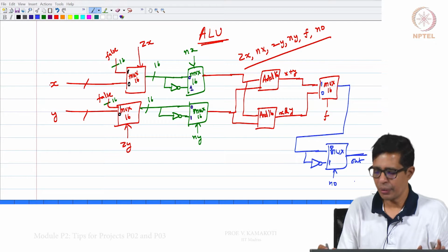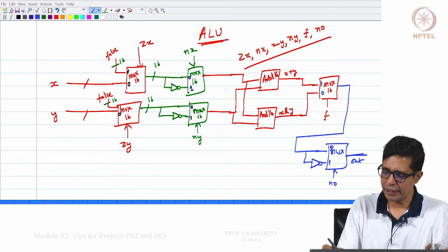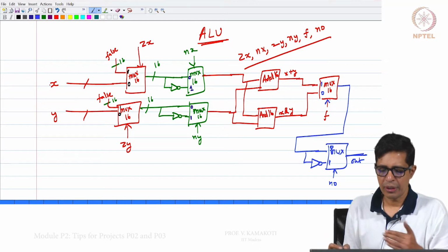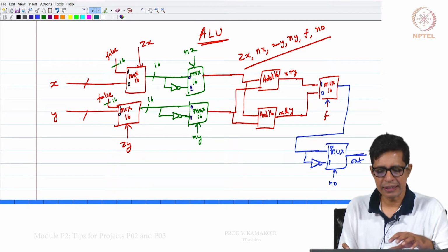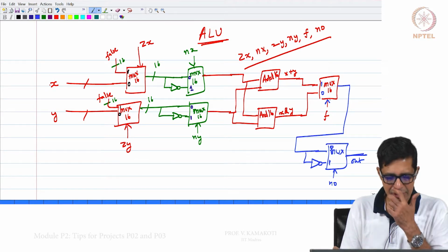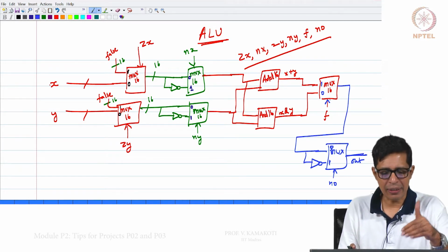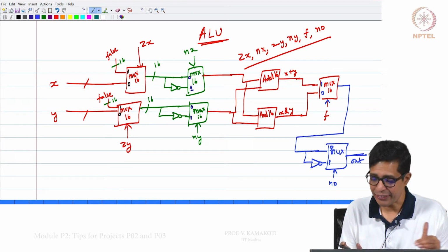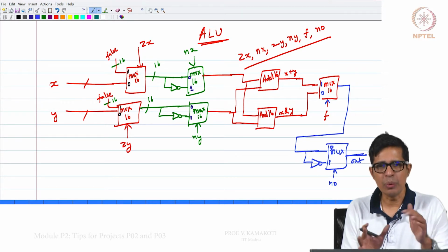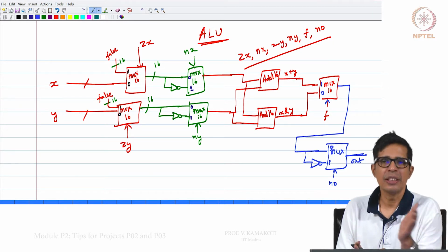Okay. So, now you actually see how the control signals are playing a role and how the data flows. Note that the control signals basically guide the data through that path. Which data should go where, the control signals decide. All the control signals go to the multiplexers here, and so the multiplexers route which data has to go, deciding at every stage what data needs to proceed.